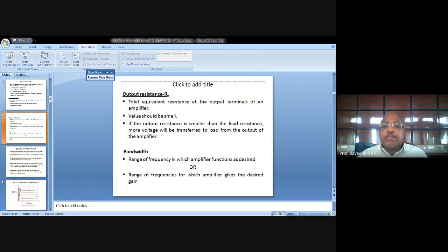Now, if you increase the base current, of course, you will be getting a graph like this for different VCE. As VCE is increased, IC is almost constant. There is no appreciable change. That is why this curve is almost parallel to the x-axis. Similarly, you will be getting one for another IB. Again, the current increases and reaches a point from where onwards the current IC is almost constant like that. So you will be getting a set of graphs like this. And this is what is called the output characteristic. That is the plot between VCE and IC for different constant IBs like this, isn't it?